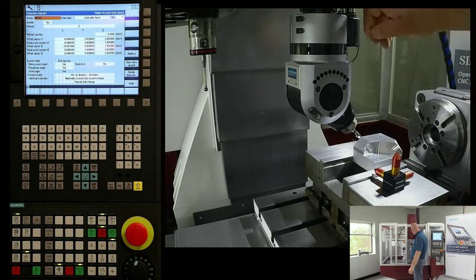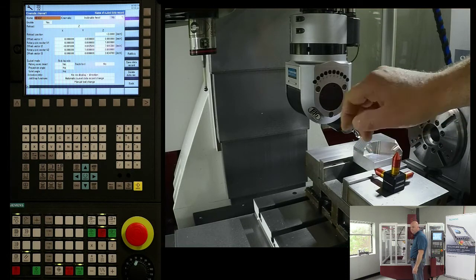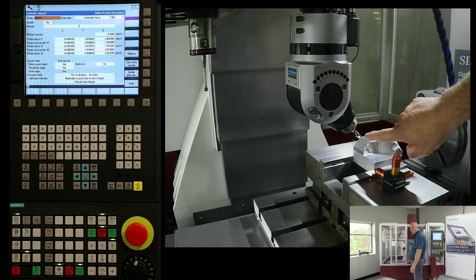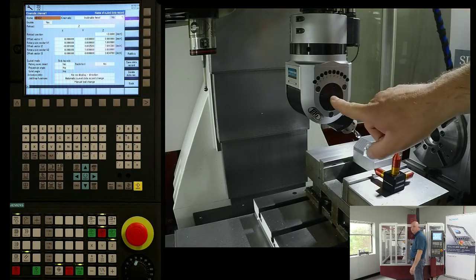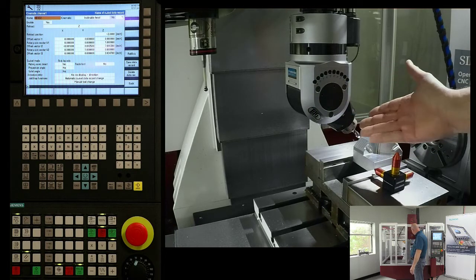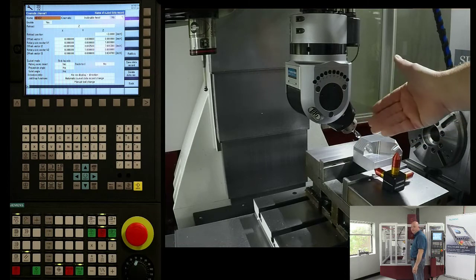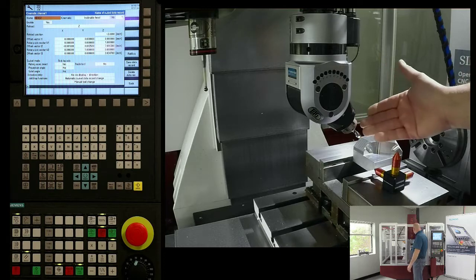I need to know a distance from a gauge line value, so probably my spindle face, to a center of rotation. I need to know a distance then from the center of rotation out to the tool tip. Now, this value is a constant, obviously, distance from spindle gauge line to center of rotation. And then what I want to do is I probably want to make a constant at least out to some datum here. Not all the way to the tool tip, because that's going to change, right? As I put different tool offsets into the machine, that is going to change the value that's there.